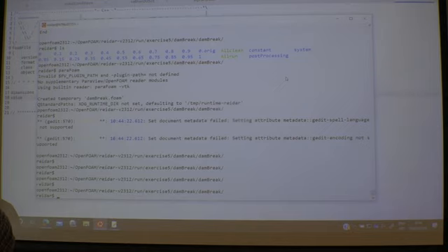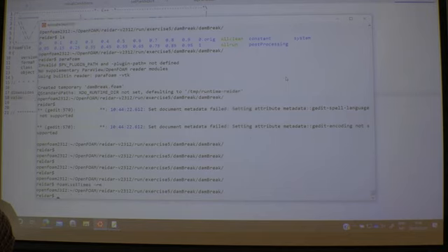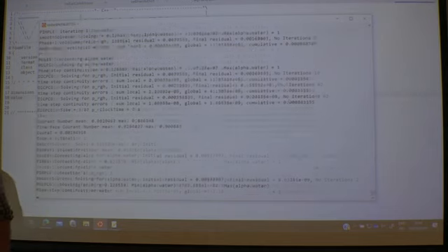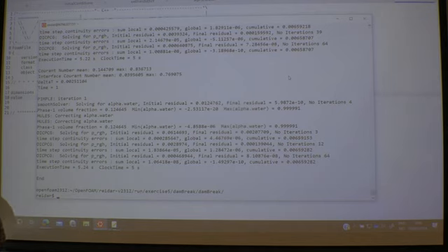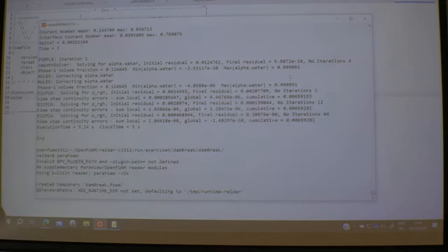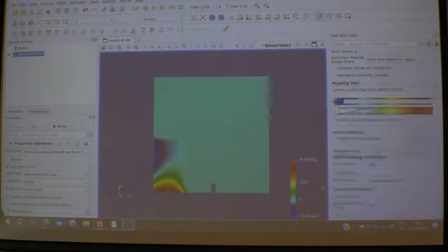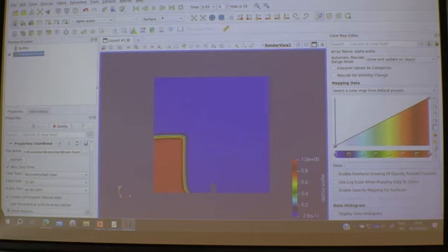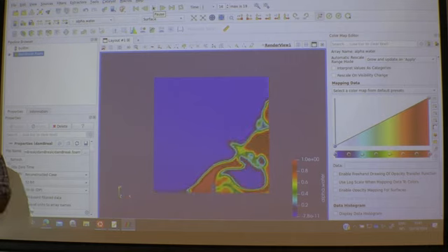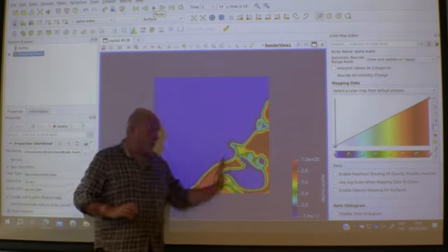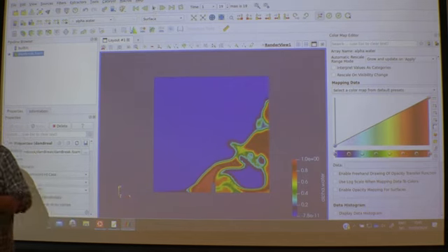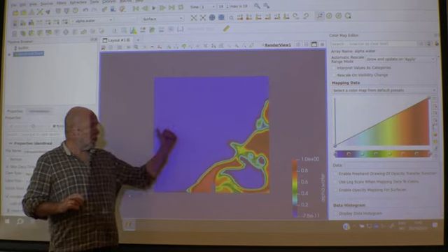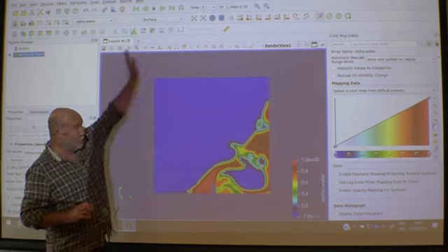I think we can just remove the results here with rm and just run again. I mean, I haven't changed the mesh or anything, so interFoam. Here we go. So let's have a look at this one now. Apply, and then we had the alpha, and then we run. And yes, now the water is going to end up, say, in the down right corner, since I changed the gravity. And if you change the gravity, say, going in that direction, then he's not going to splash at all, but he's going just to flow out.